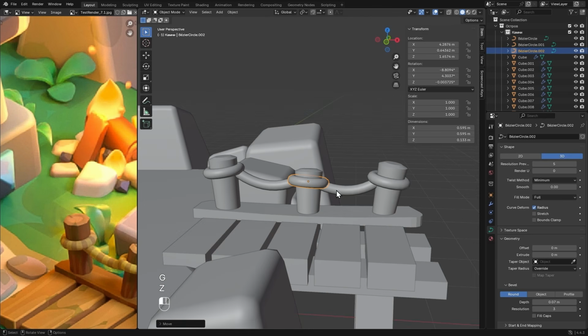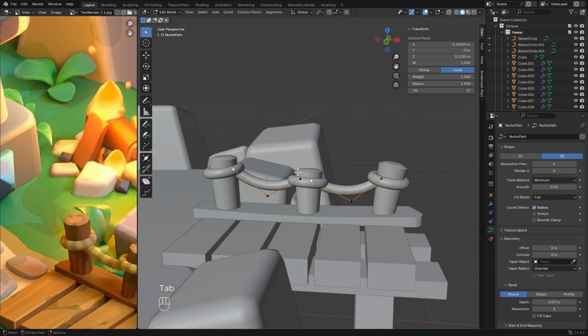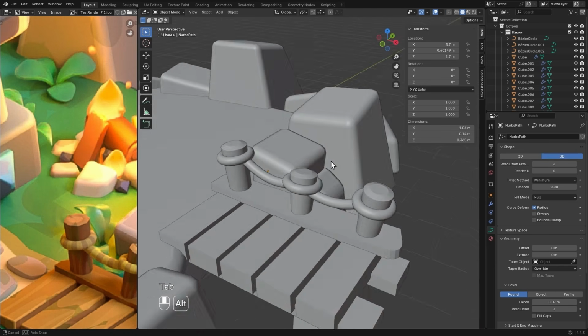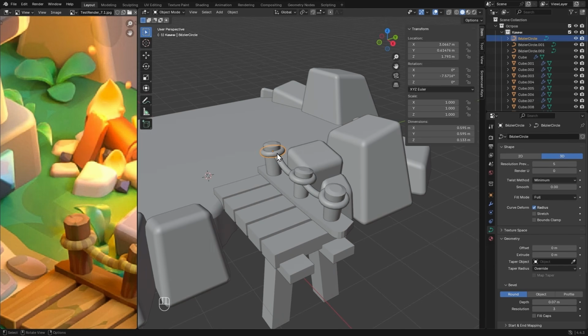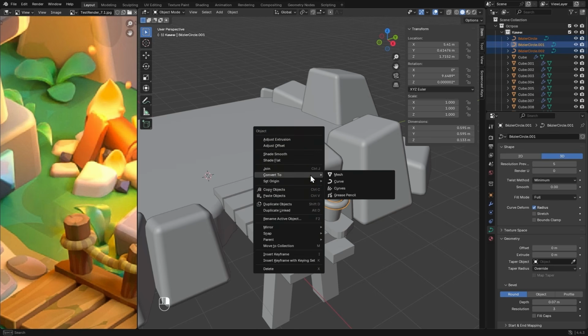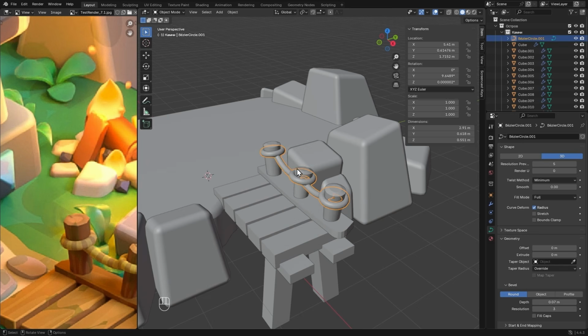I think in this case, we can lower the curves at these points just a bit. Excellent. Now let's select all these curves holding Shift. After which I'll right-click and choose the Join function, meaning to merge them. Now it's a single object. We can change the thickness of these ropes if you need to. I'll change it to 0.6 meters.